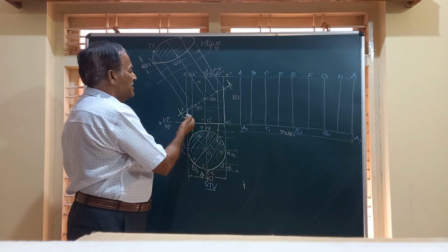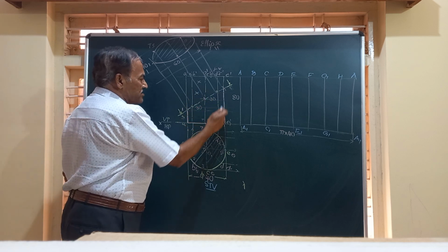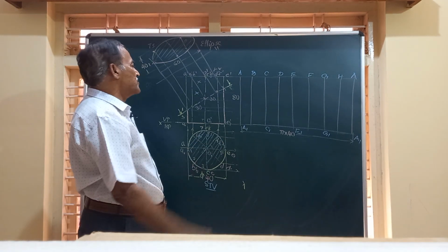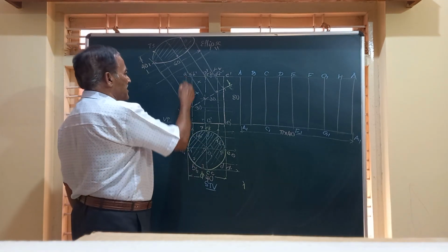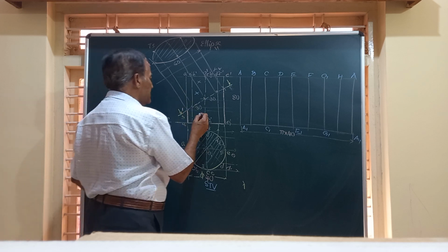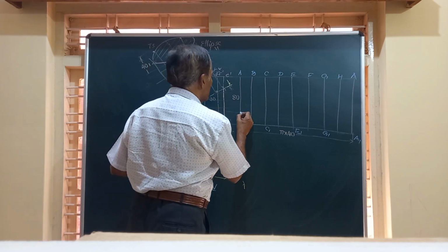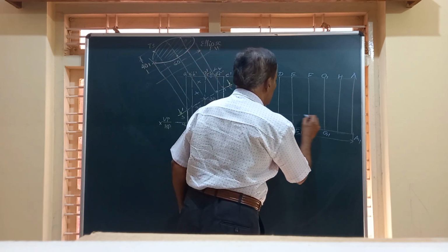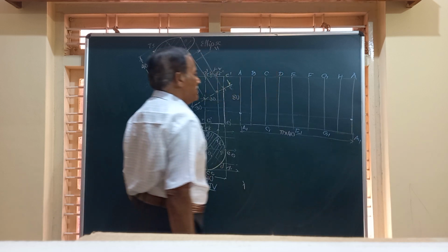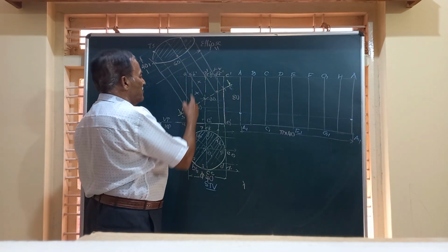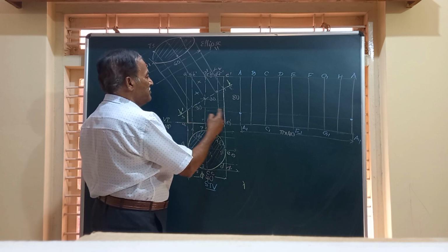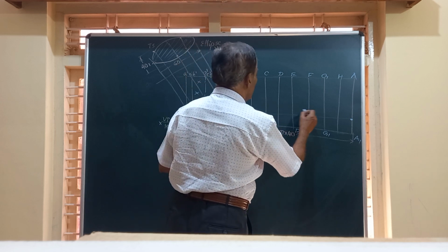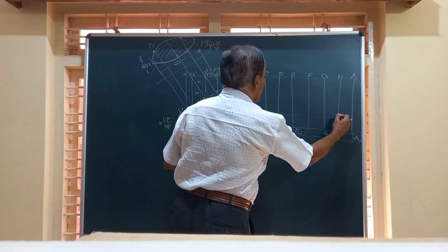We have the section plane. We know what is the part that is retained. This bottom part up to the section plane is a lateral surface, and that I have to show now. Let me start from this AA. AA is cut here. So I will draw a horizontal line from there to cut AA, this generator, and also this generator. So you will have one point on this. Then from here we are going to have points on BB and HH. So this is BB, and same height you are going to have HH.